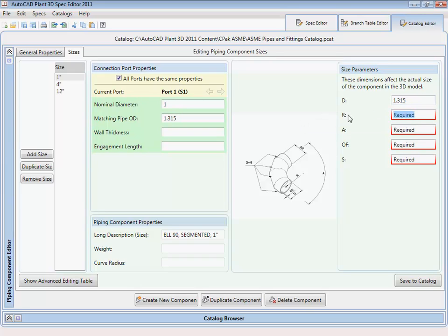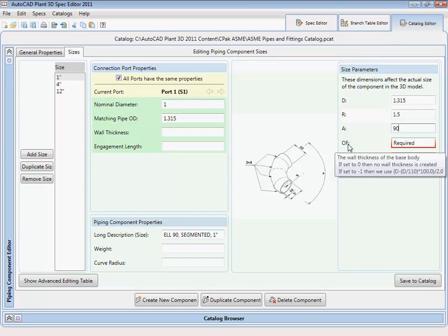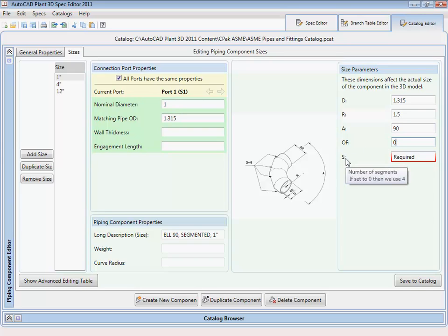If we hold the mouse over a parameter name, we will get a tooltip. These tooltips are important to pay attention to because many parameters have special values for default. A special value might be 0 or -1. Special values indicate that we want to allow the model to calculate a default. This is especially helpful as the models become more complex.